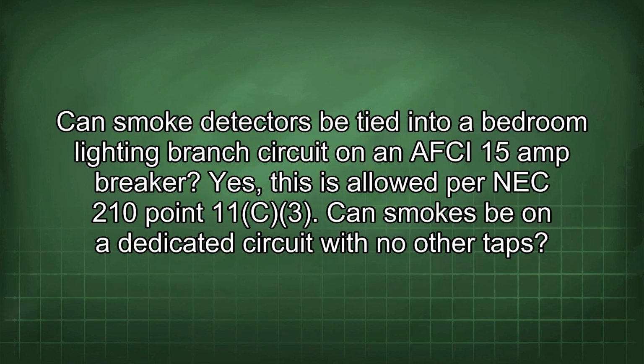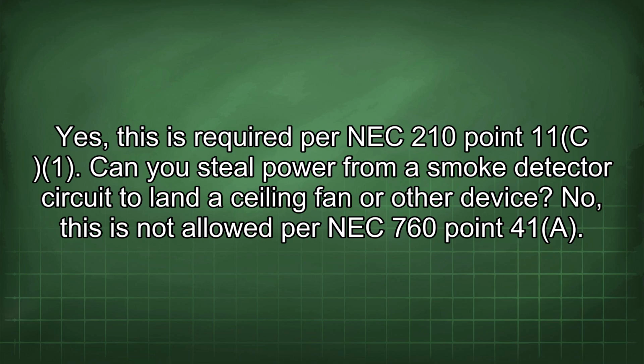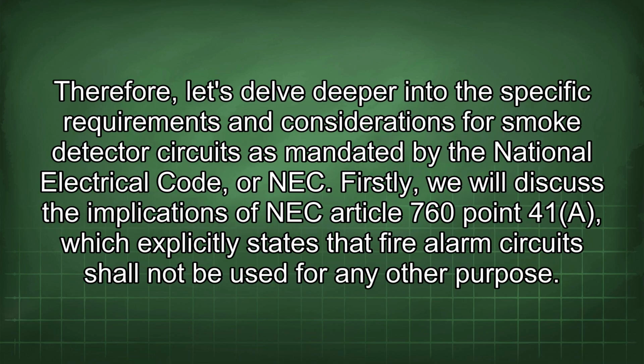Can smoke detectors be tied into a bedroom lighting branch circuit on an AFCI 15 amp breaker? Yes, this is allowed per NEC 210.11(c)(3). Can smokes be on a dedicated circuit with no other taps? Yes, this is required per NEC 210.11. Can you steal power from a smoke detector circuit to land a ceiling fan or other device? No, this is not allowed per NEC 760.41(a). Therefore, let's delve deeper into the specific requirements and considerations for smoke detector circuits as mandated by the National Electrical Code, or NEC.